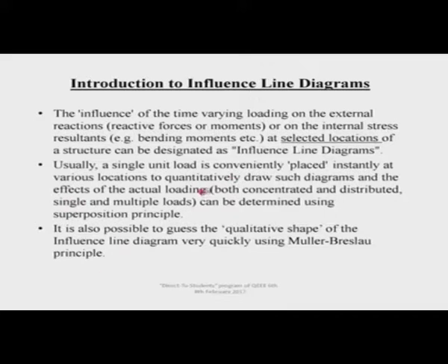So, usually a single unit load is conveniently placed instantly. I say instantly just to give an equivalent static effect at various locations to quantitatively draw such diagrams, and the effects of the actual loading, both concentrated and distributed, single or multiple loads, can be determined using the superposition principle. It is also possible to guess the qualitative shape of the influence line diagram. We will discuss using a principle called the Muller-Breslau principle, which is a very, very powerful tool in structural analysis. You will see that.